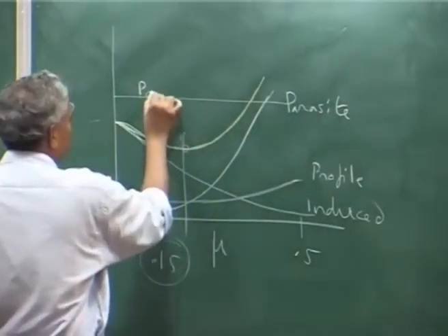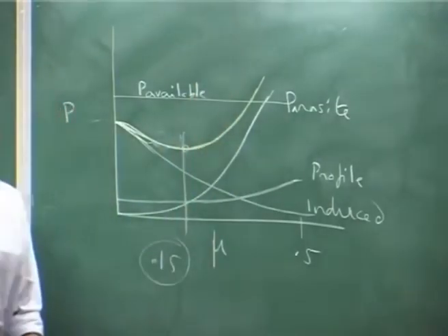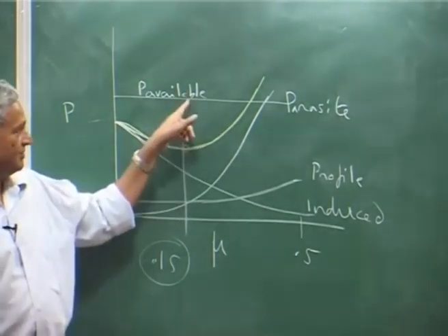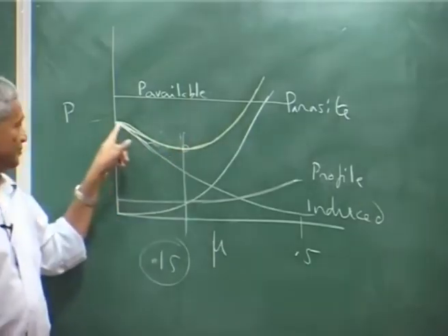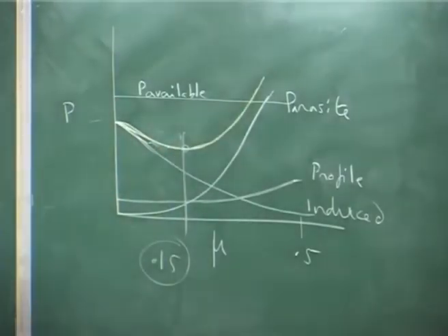This is P available, at any time, assuming it is sea level, but as you go to high altitude, power available will come down. Power required, because of induced flow is more, will go up. Here you will have this much excess power for climb. If you go here, it is very less, but if you go to high speed, the power required to climb is less.